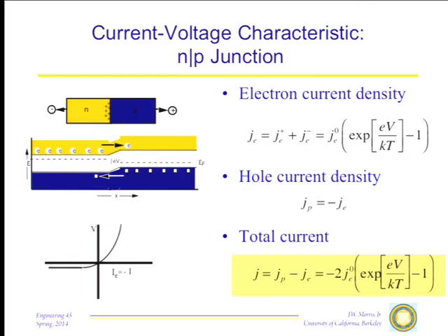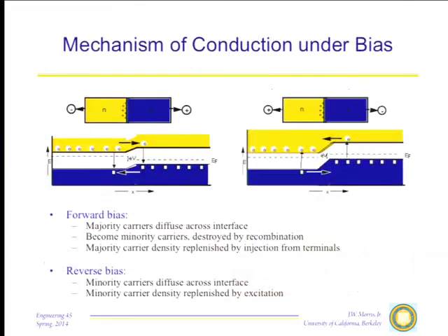To all intents and purposes, forward bias, this is a conductor. Reverse bias, for all intents and purposes, it doesn't conduct at all. There's a small leakage current, but we can usually ignore that. So this is a one-sided conductor, an asymmetric conductor. Put it in forward bias, electrons charge forward. Put it in negative bias, the electrons don't move at all. Well, tiny bit, but essentially not at all. So we have a device which is an asymmetric conductor.